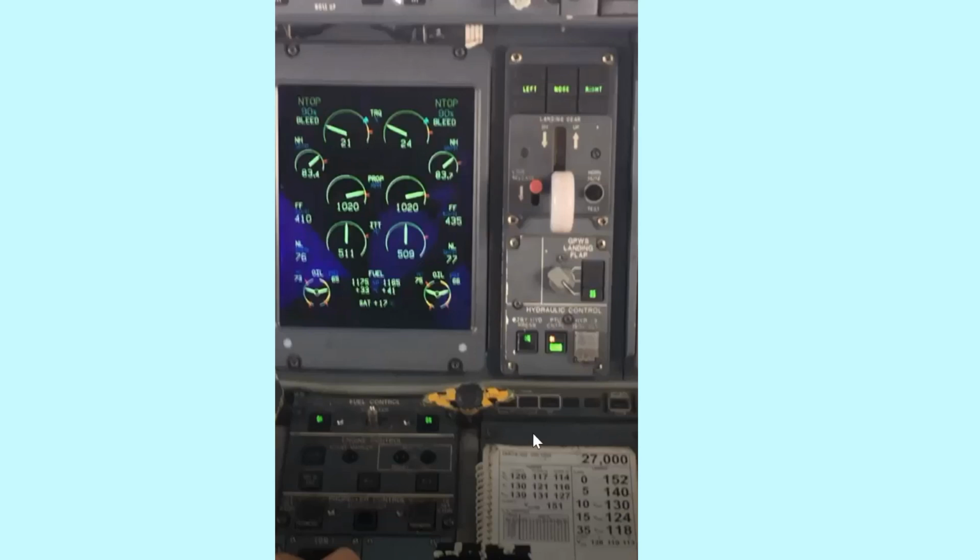And that is all with the autopilot telling me that, look, for the aircraft, or for me, meaning the autopilot, to maintain this pitch and that speed, you must set that torque. Okay, now it is maybe a coincidence that the first two digits of the landing weight are actually our percentage for the torque values for the configuration of the aircraft. Okay, in the landing configuration with flaps 35. I hope that makes sense.